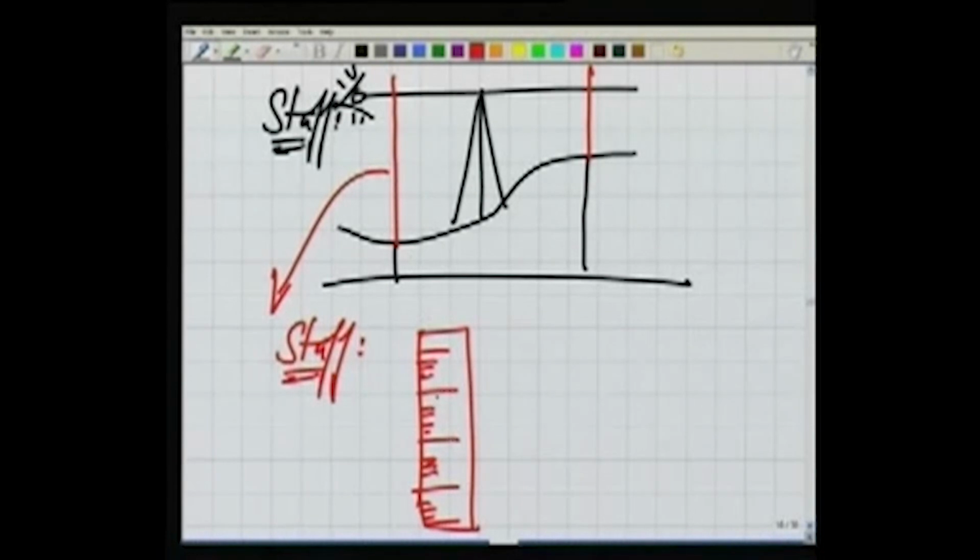So these are basically vertical scales like this, and someone is holding this vertical scale here so that it is kept vertical, and we have the graduations. So from here, when we are observing, we are taking the reading RA at this point A, and if this is point B, we are also taking the reading against this staff, which is RB.